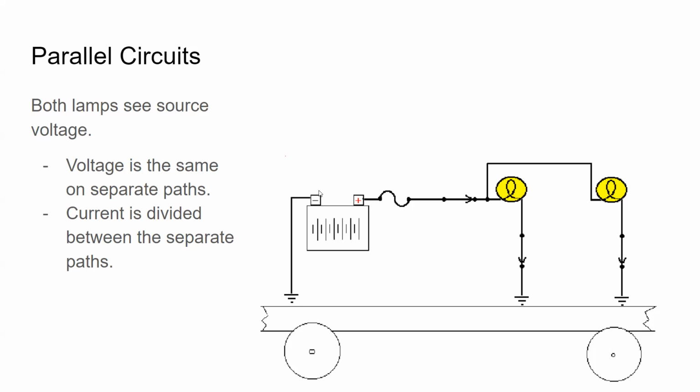And from that switch, if we were to measure, put our black lead on our test meter over on here. Let me switch to black. All right, we put our black test lead right there. And then we put our test lead here. We'll have 12 volts, right? Other side of the fuse, 12 volts. This connection going into the bulbs will have 12 volts. So we've got 12 volts feeding both of these light bulbs. If we measure here on this light bulb, we've got 12 volts. If we measure here, we have 12 volts. This is ideal. This is exactly what we want.